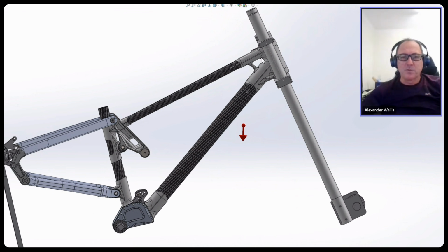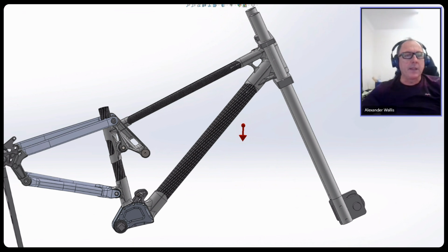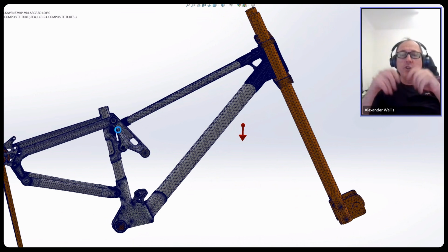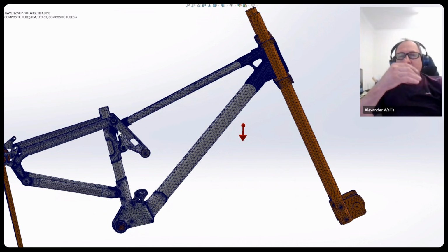So you could do a very simple finite element, which is just a beam model, and you'll get pretty good results. You will be able to see that you've got high shear and bending moments in different areas. Now, with the computer power we have nowadays, we can refine that so much that we can create very detailed meshes with a very high number of these little elements, and for each of these elements we solve a calculation. The finite element means you take this little line and you do the calculation on that line. How much does it deflect under how much load? And you keep doing this calculation every time you have an element.